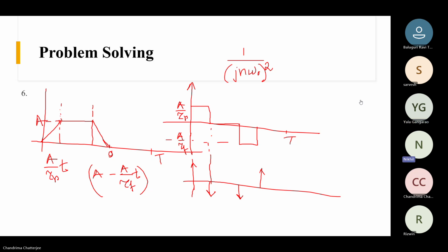But when we are designing any converter or any application, at the design stage we have to do some tests, right? For example, for radiated emission, we have to see while design stage only we have to do some radiated test. We have to do some conducted emission test while design only.